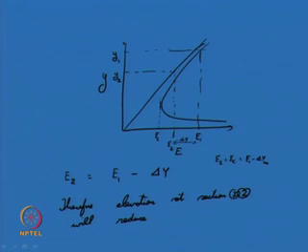That is not theoretically possible at all. So, what happens? Your energy at section 2 will remain at critical condition, that is whatever is the critical depth and critical flow. From there, you need to add del y m. So, Ec plus del y m. Okay, I will just give it in the next slide.